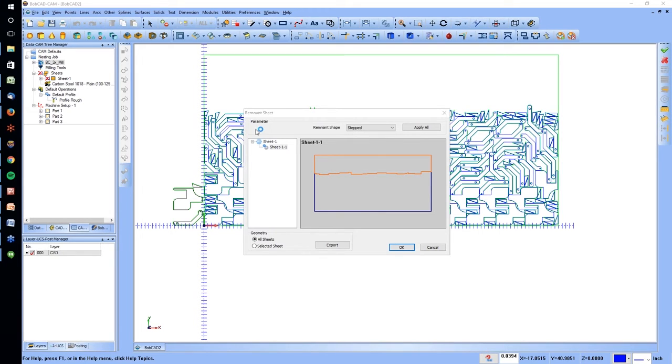All right, we have another good question here, and then we'll go over the sheet remnant option that pops up for you guys. Can you do engraving or pocketing cuts on shapes that have been nested? Yes. What happens is, if the actual original part had a pocketed area, you can go in and add that area as a pocket, or if you have lettering you want to engrave, you would be able to go in and add it to that particular part. It would have to come in with the original piece, but you can switch it to an engrave or a pocket. Once they're nested out over here, the only way you would be able to do that is to export the sheet as a DXF, add in whatever options, and then throw toolpath back on each individual part, okay?